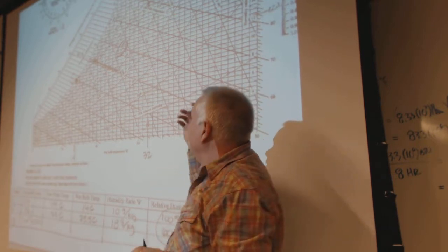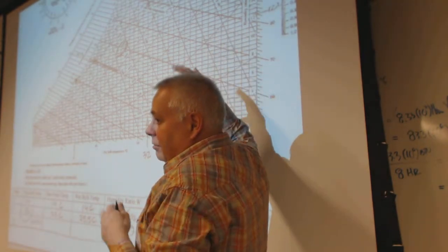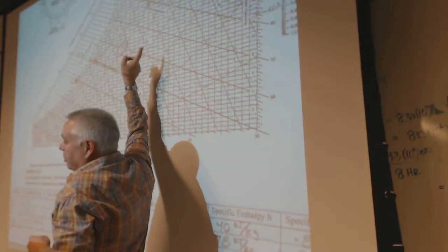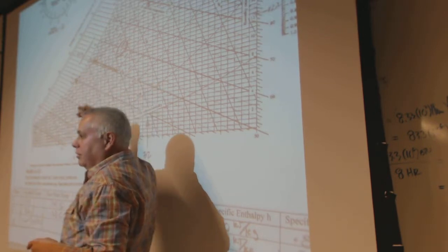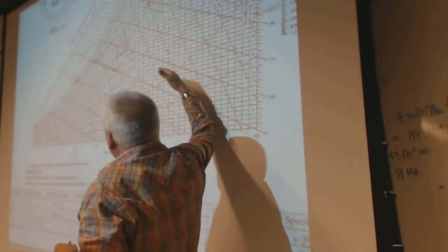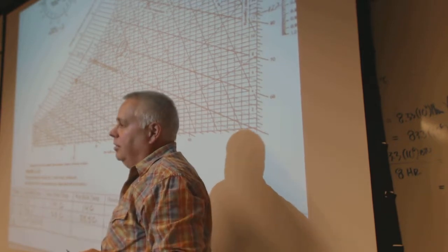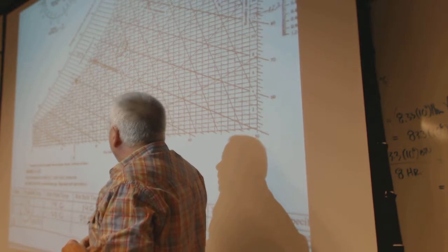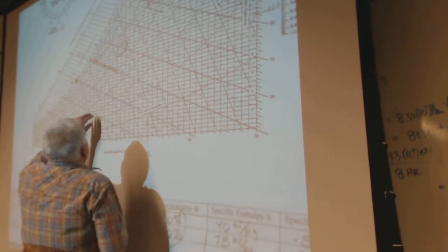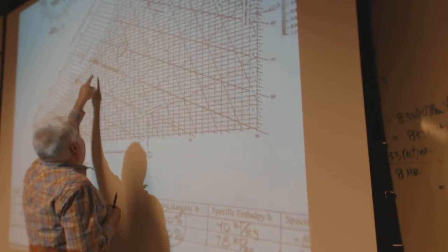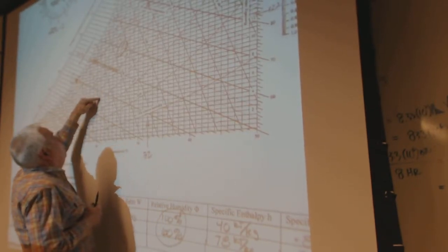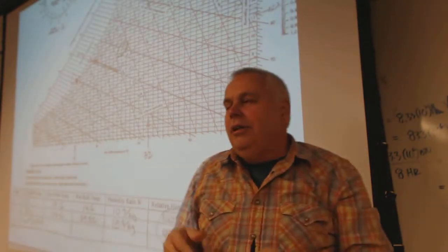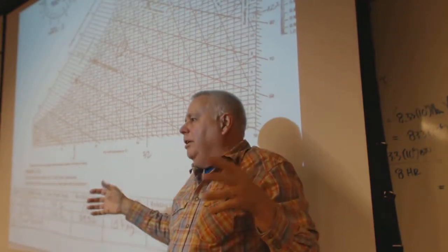If you use the chart, I mean, you can find the information without the chart by doing what we did. But with the chart, locate the 2 points, draw a line between them, find one or the other of those, conservation of mass or conservation of energy, and where it intersects the line, that'll tell you the output state. And now we know the mass that's coming out. If we have this volume, now we know the volume's probably 0.84. It's more than halfway, call it 0.846. Now the volume flow rate coming out, we can figure out.